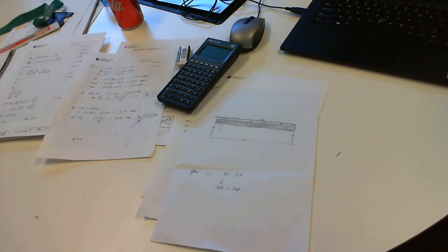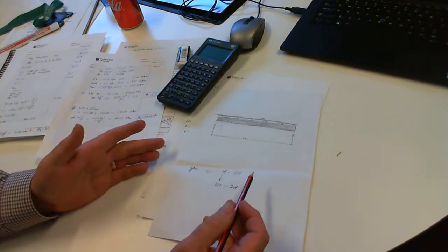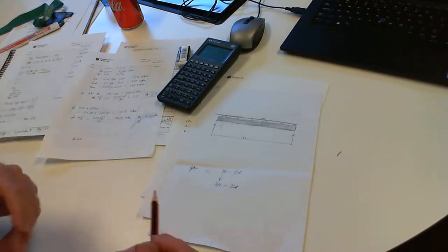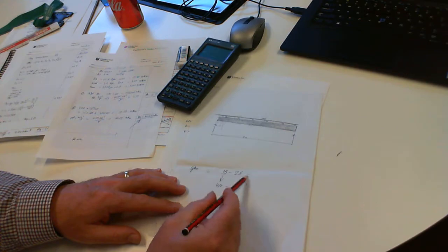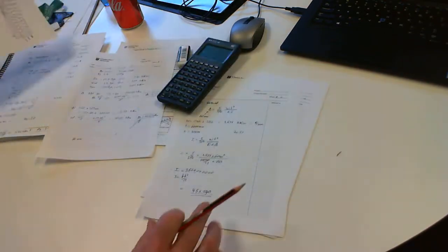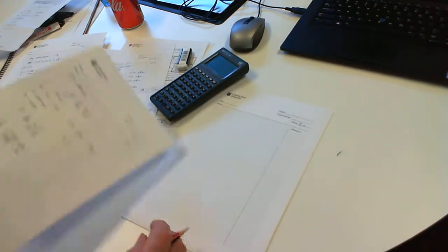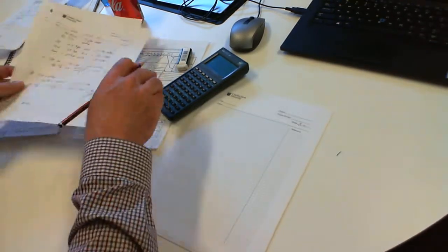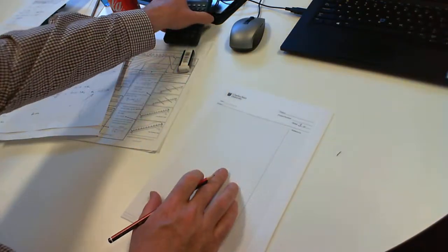Just so you know, when you're in steel, you should be looking at ratios of between about span on 25 and span on 40. Sometimes span on 50 if you really push it to the limits. But these are your typical ratios for timber, which is what we have. So we'll go to page 3 now, and we're going to work out first the strength of this beam in bending.